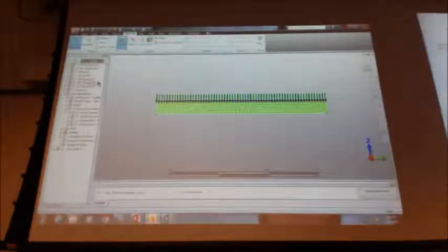So most of the time we're going to use quadrilateral elements and maybe use the triangles to do the refinement, but quads are going to get you there much faster with fewer elements, so you don't have to do as much. But you can do the theoretical solution, and then you need to have your model converge to that solution. So, any questions?